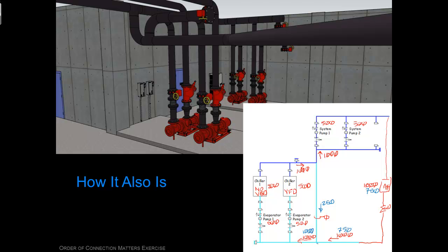But because the water blends before it goes to both of them, because this T is right here, that means that for this plant, the way it's piped, both machines are going to unload uniformly in terms of percentage. These are two equally sized machines, and so at 75% load, they're 250-ton chillers, so they would have dropped back to about 225 tons each, a little under that.